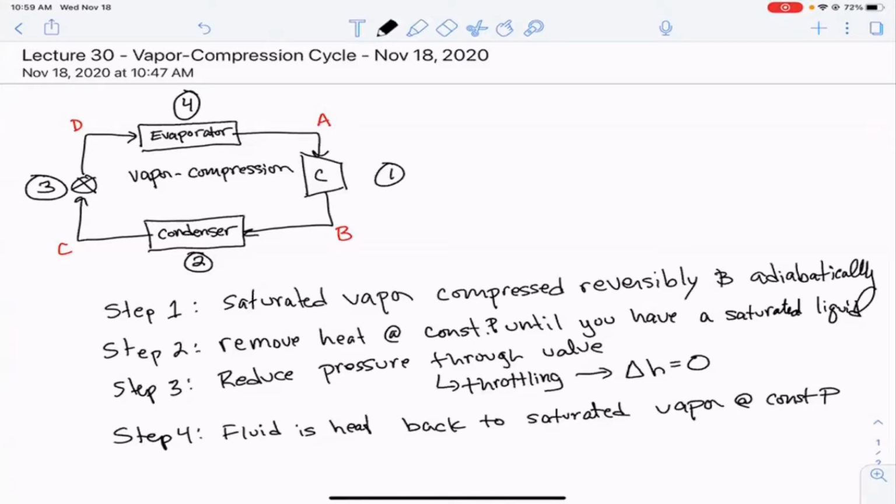But in the vapor compression cycle, we actually are also operating between 2 pressures, right? And they're 2 saturated states. And this is something that's kind of important for us to think about, is that A is saturated vapor and C is saturated liquid. And so when we're operating on this particular cycle, where we are on these sort of property energy diagrams is going to be very specific, right?